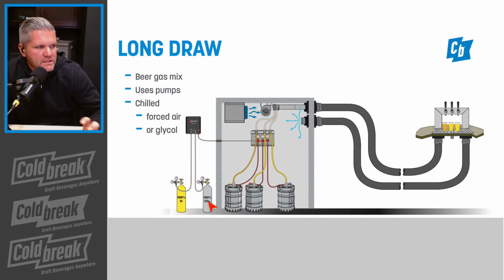The downside to doing that is with CO2, you can compress a lot of CO2 into a smaller tank, like a 5-pound tank, and at a certain temperature, that CO2 will turn into liquid. That same amount of nitrogen takes an extreme amount of pressure to get into a tank, and it operates at a higher temperature. So CO2 and nitrogen don't typically like to mix very well.